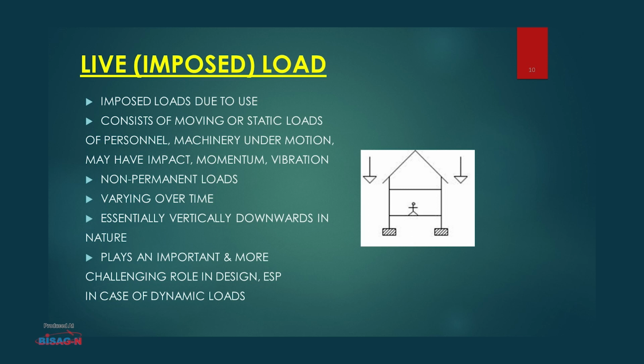Next is imposed load, also referred as live load. Live loads are created due to usage of the building. It consists of moving or static loads of persons, machinery under motion, etc., and may have impact, momentum or vibration. It is a non-permanent load and varies over time. Live loads prescribed by codes are conservative and empirical, based on experience and accepted practice.